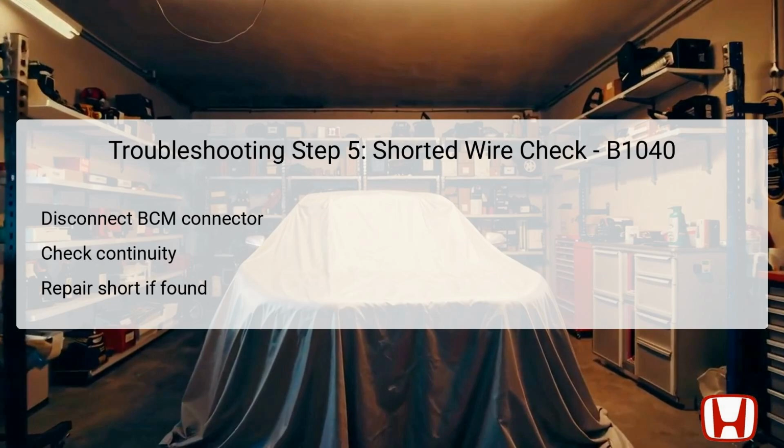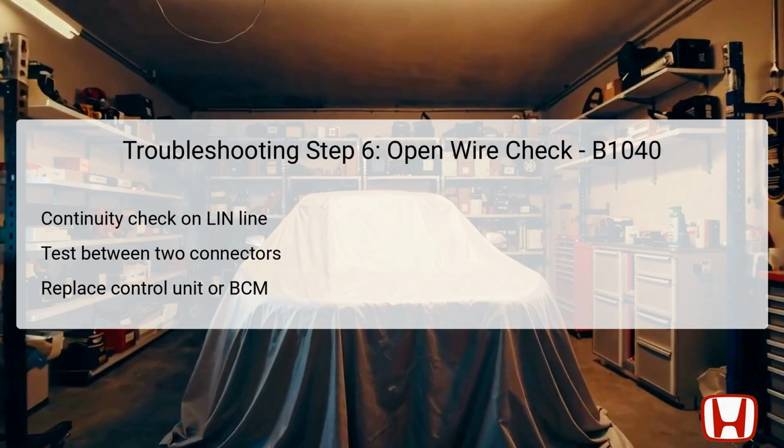If continuity exists, it suggests that a short circuit to ground exists within the wire. This will require the repair of the shorted wire to restore functionality. If no continuity is detected, it indicates that the LIN FR wiper wire remains intact, allowing for further testing to continue. The 6th troubleshooting step involves performing a continuity check on the LIN FR wiper line.